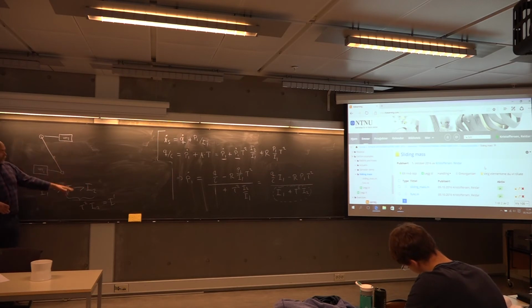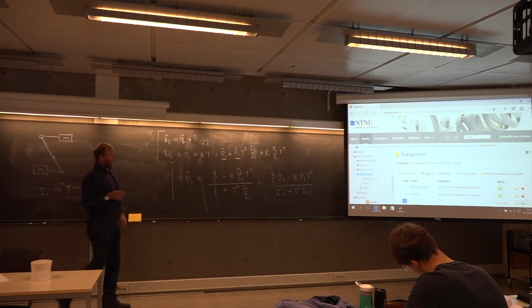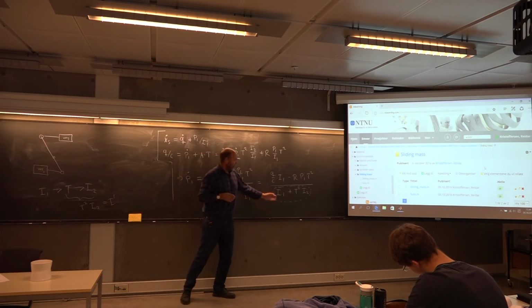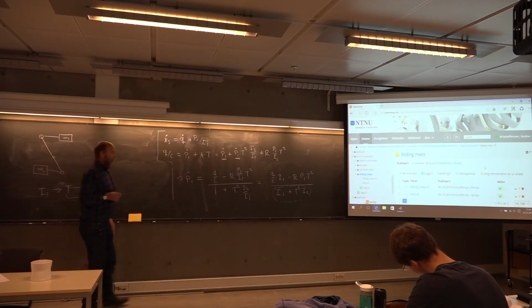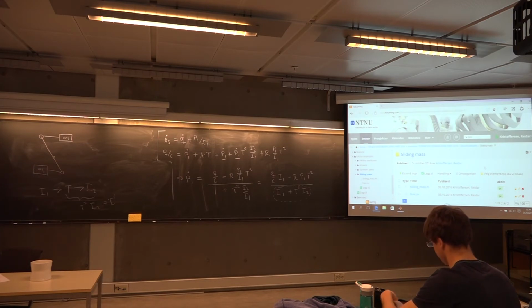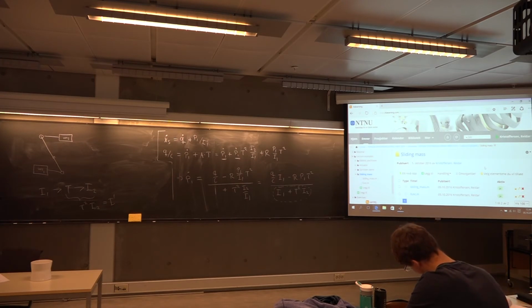The sad thing was that I had more than just the inertance on the other side. I had the damper as well. So we couldn't really do it. Here it would be possible actually to calculate everything using this virtual mass or equivalent mass, but rather tricky. Easier then to do it the straightforward way here. Okay, any questions to this one?